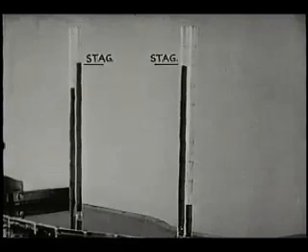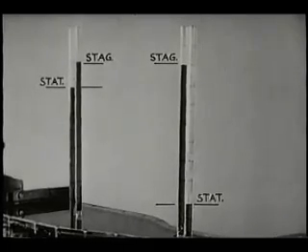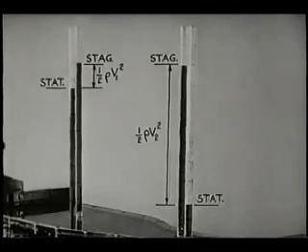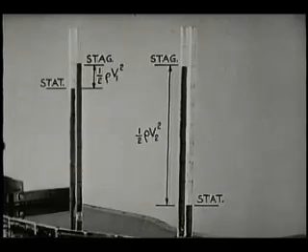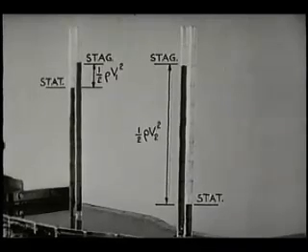We've placed pitot tubes at the upstream and downstream cross sections of the contraction, and these are the static pressure manometers we had before. The difference between the stagnation pressure and the static pressure is the local dynamic pressure. So this is a way of measuring velocity. Because of the area contraction, both the dynamic pressure and the static pressure change. But the sum of the two, the stagnation pressure, remains constant, which is what Bernoulli's integral told us.